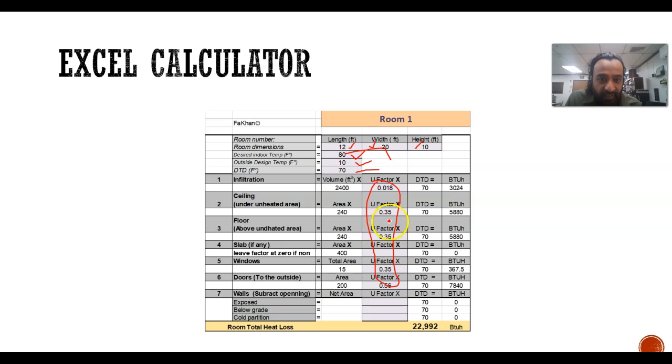If we look, most of the heat is lost from the ceiling and the floor, and that is a red flag because you need to account for that and put some insulation. That's something you can work with completely. I'd rather lose heat to infiltration than to ceiling and floor, because that's heat that is not useful for you. You can lose heat through heat exchange, but you're getting freshly nice, clean air, instead of losing heat just for no reason.